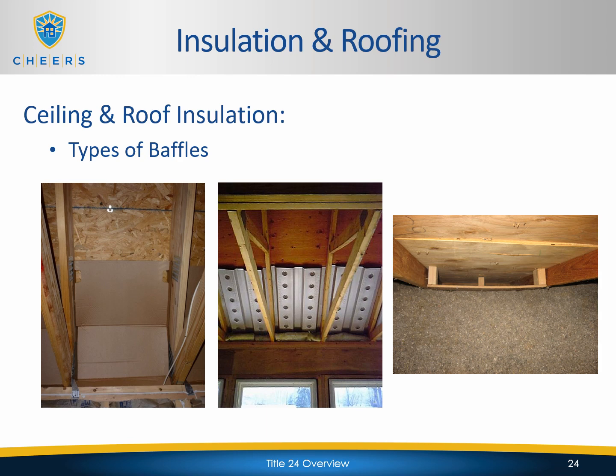In the middle example, those are actual baffles built specifically for that purpose. So it's a product that is bought and installed for that specific purpose. And then on the right-hand side, it looks like field-fabricated baffles, literally some cut 2x4s and plywood to keep the insulation in place and keep it from covering the vents. So each one of these examples is perfectly okay, as long as it's doing what it's supposed to be doing.